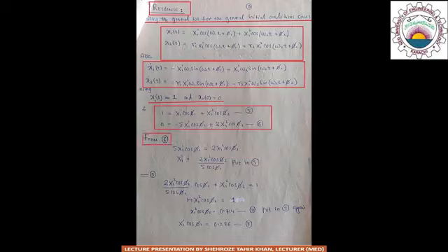So from equation 6, the value of mode shape x11 is found in terms of the mode shape x21 and phase angles phi 1 and phi 2, and then this value is substituted in equation 5 such that we have x21 cos phi 2 is equal to 0.714, and it is called equation 7.